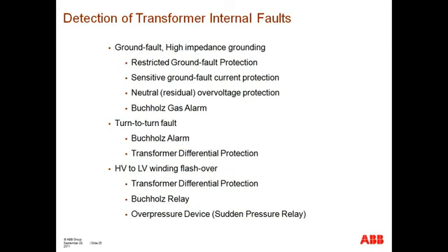In the case of turn-to-turn faults, detection depends on how many turns are involved. These are going to be faults that may or may not be detected by the transformer differential function. That's why there are new elements and techniques used to detect these types of faults, which we'll discuss in a few slides. And then you have your Buchholz alarm that could assist in identifying these types of faults. And then you could also have the case of a high voltage to low voltage winding flashover. In this particular case, transformer differential, Buchholz relay, or your sudden pressure relay can provide adequate protection.